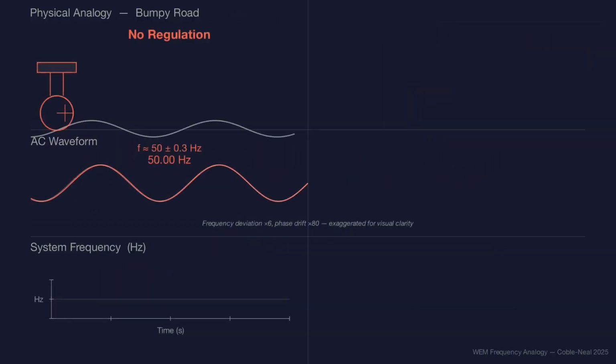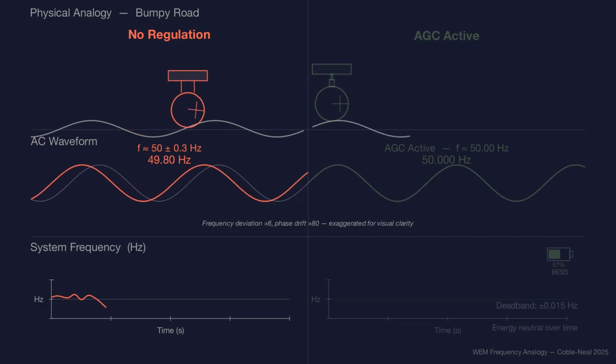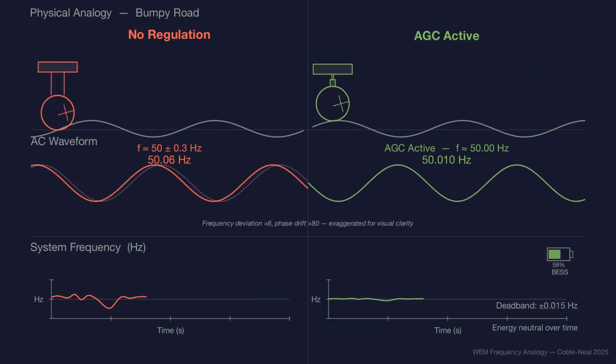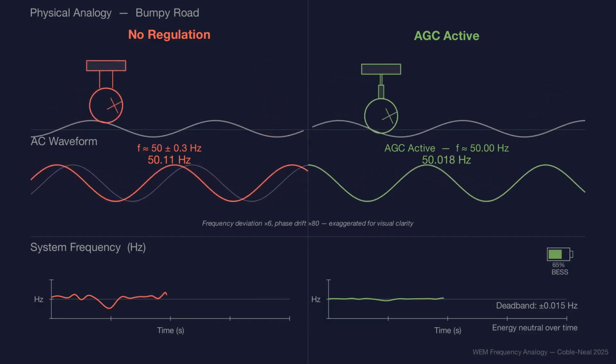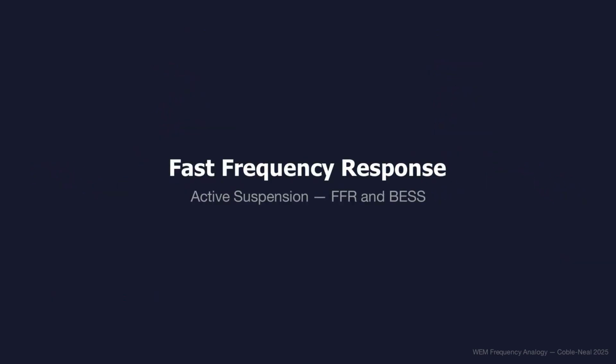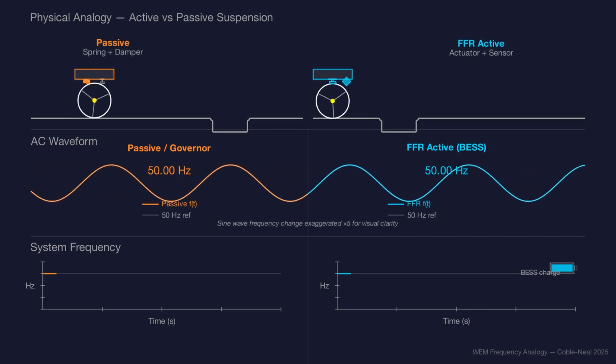The secondary response involves the system operator sending instructions to each machine it controls, mostly electric generators, to adjust their active power output. This occurs within a few seconds of a system disturbance. In this side-by-side comparison, a battery storage device is being instructed to inject active power.